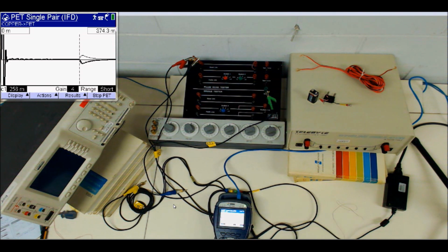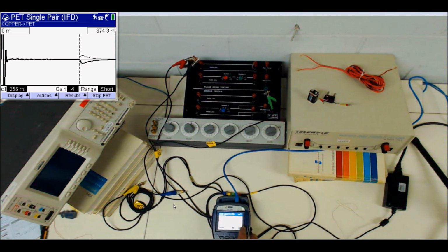So that's a very useful function for you to know and use out in the field, because it will enable you to find these faults and determine if they are actually faults or maybe phenomena arising from humidity, instant humidity on a point, or a joint in a connector on an aerial splice. And in this way you can say that when an open becomes a short, or vice versa, a short becomes an open, then it should be a splice. Usually this phenomenon is happening towards the customer premises, where we connect our pair from the ground, from the tip outside the house premise, to the actual wall socket.